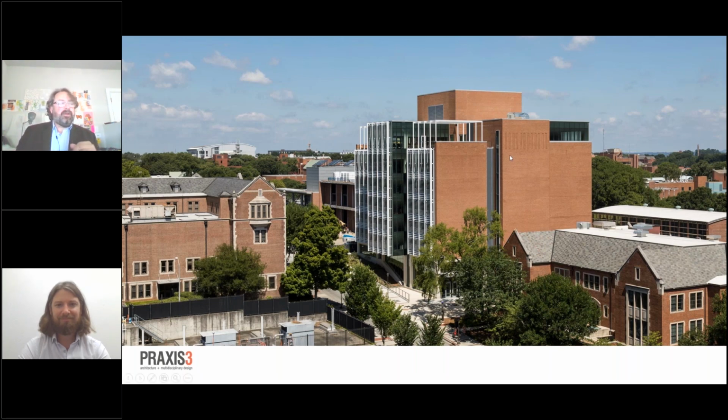We also, because this is a high-rise building and we had to do extensive code upgrades for this project, had to install larger elevator cabs, and that came along with a higher override height than the original building would allow for. So this penthouse had to be extended upward quite a bit in order to make this project work. By salvaging the brick and reusing it, we were able to accomplish that in a way that, with this truly beautiful 1960s era brick, we have fidelity to that finish across the entirety of the renewed project.